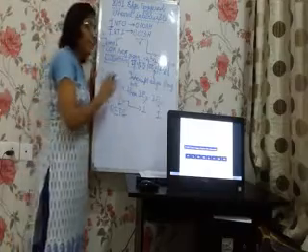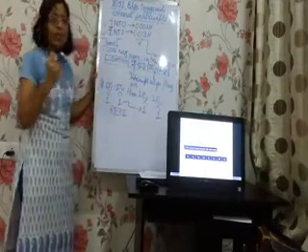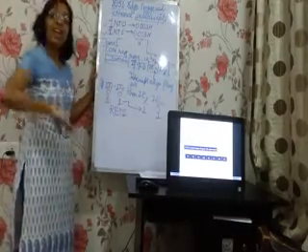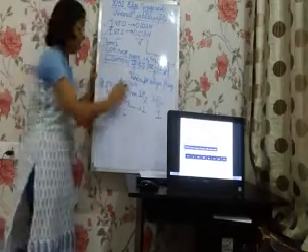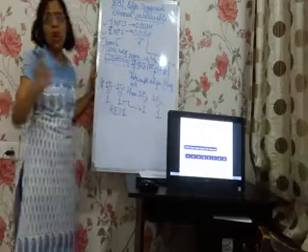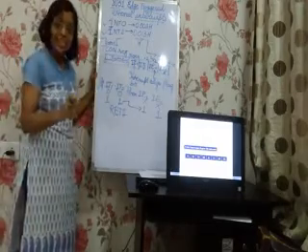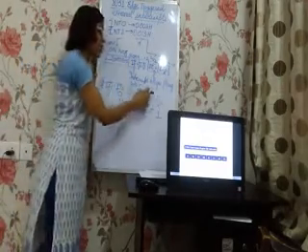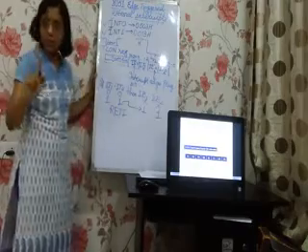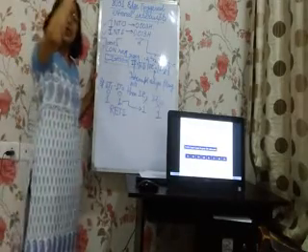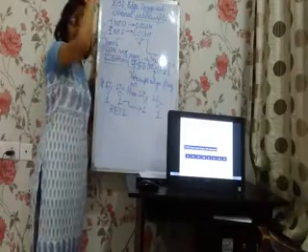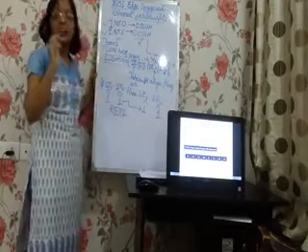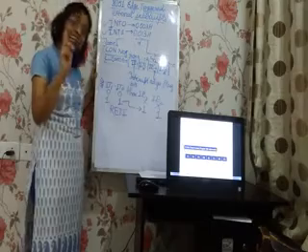So if INT1 or INT0 get defined as edge triggered interrupts, that is IT1 IT0 are 1-1, then first IE1 IE0 will be made 1, then the microcontroller will get interrupted. It will execute the ISR. The last instruction of ISR is RETI.